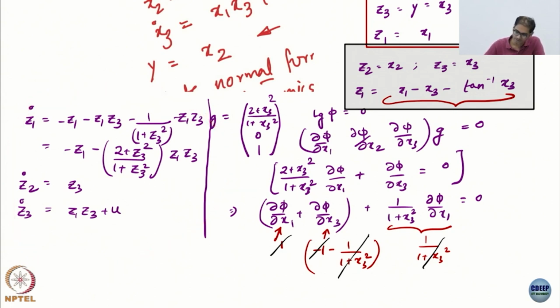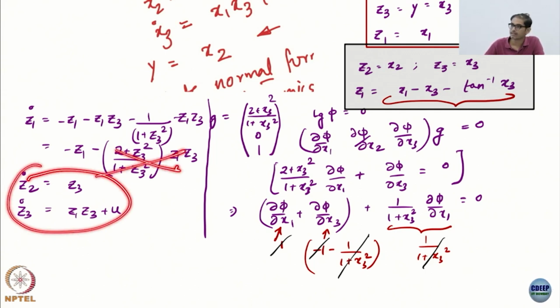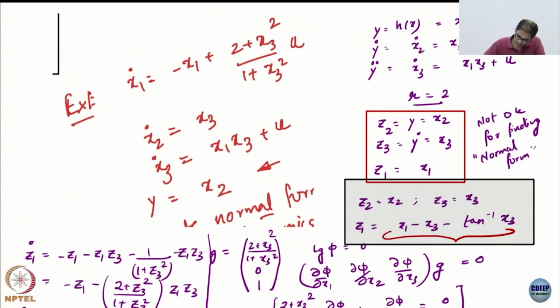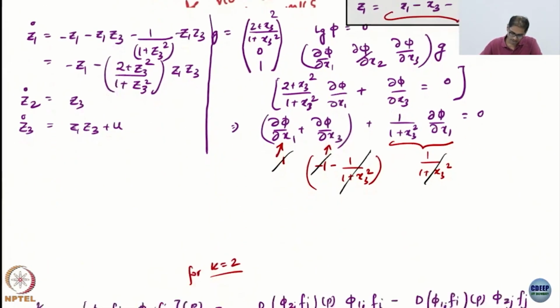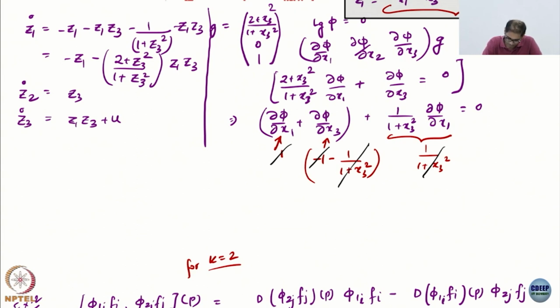You still get nice enough zero dynamics, by the way. Because if the linear part goes to 0, this guy is 0 and this is again an exponentially stable system. So again, started with something complicated and very non-linear, not evident how I would design a control based on any methods that I know, but I still end up with something rather nice.